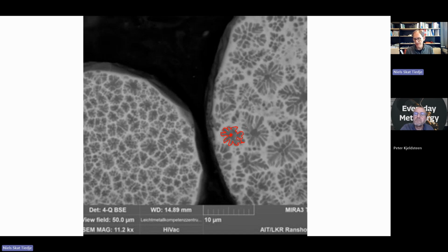So we should imagine a small tree growing in the liquid, and that solid, the tree, is pure magnesium. And the liquid around the tree, as the tree grows, becomes more and more rich in nickel. And therefore, in the area we have out here around it, that is a liquid with high nickel content. When we get to the eutectic point,